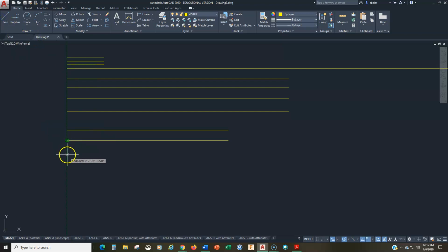Yep. Okay. Let's look at this again. So we can go 2 foot 6. Can I do just a 1/2 without the dash? No, because AutoCAD would interpret that as 2 foot 6, 1 over 2. Okay, so really we can't do that. Dash 1/2.